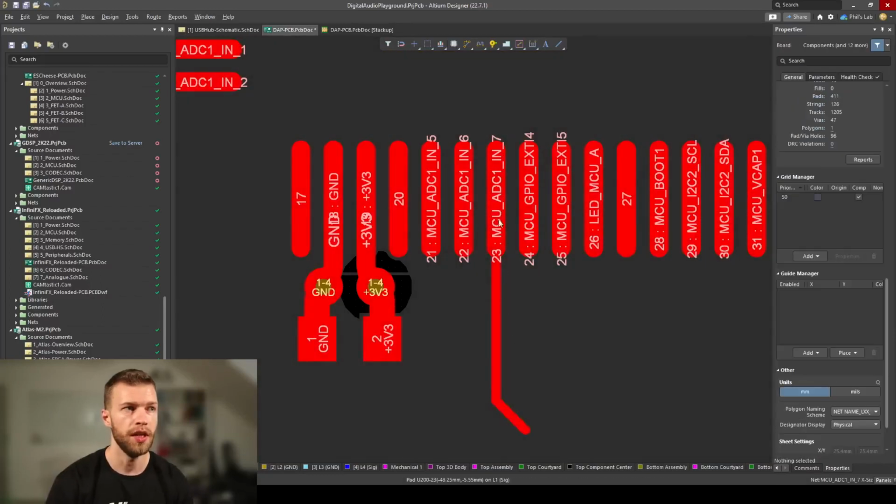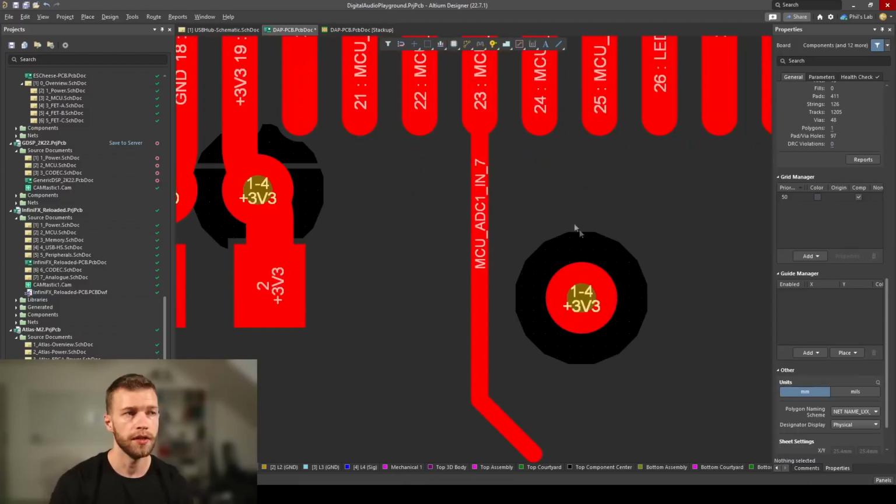You always want to keep any signal trace running adjacent to a reference plane. This is ground typically, but can also in certain cases be a power plane. So remember to route signals and power over a reference plane. In certain cases, of course, you might have to route your signal traces close to vias of different tracks or not ground vias. You can see as I move this power via around, below in Altium, I can see the ground plane has been voided. Of course, I have to keep some clearance between different net vias, pads, planes, and so on.